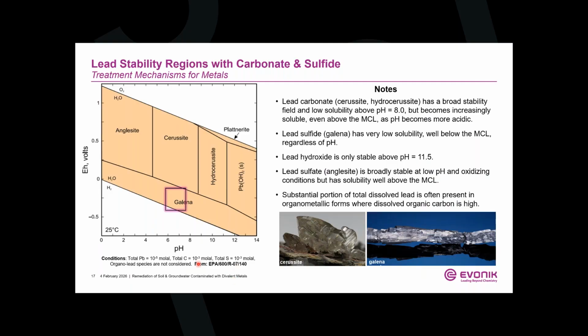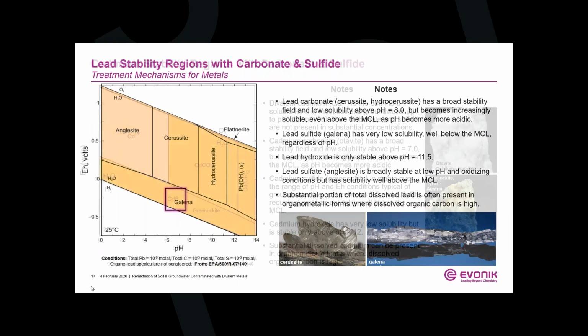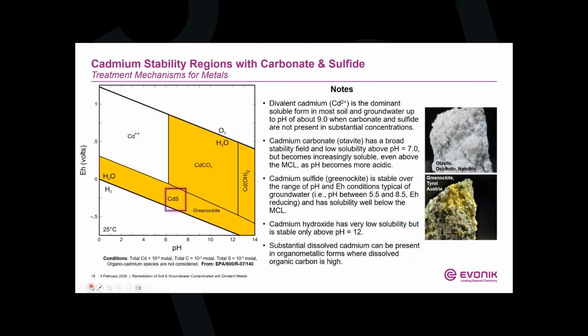And here you have the standard conditions and the reference where that diagram was pulled from, and a couple nice photos of lead hydroxide and lead sulfide. Looking at another one of the divalent metals that we commonly need to deal with, cadmium, same thing. That same sweet spot will work well for precipitation of cadmium.